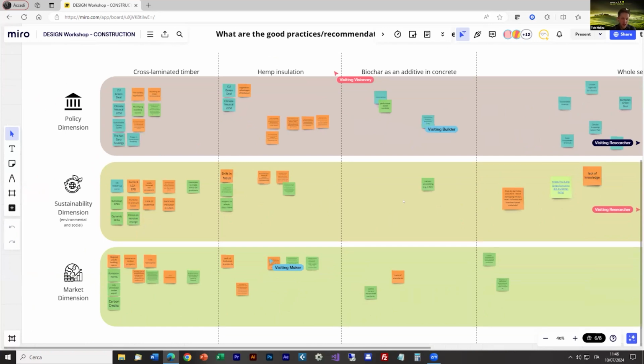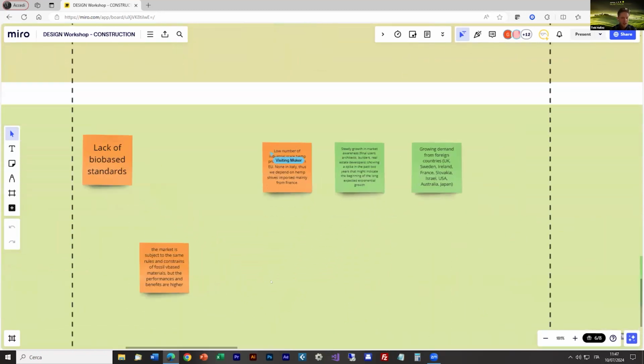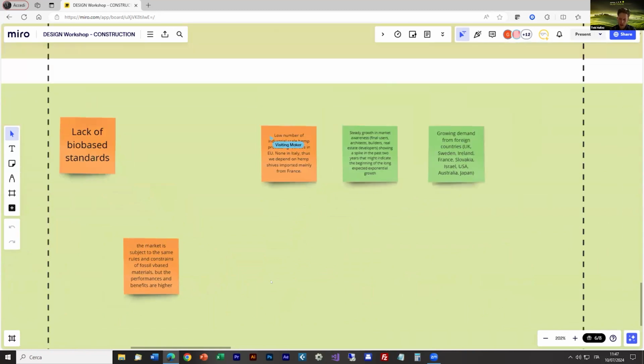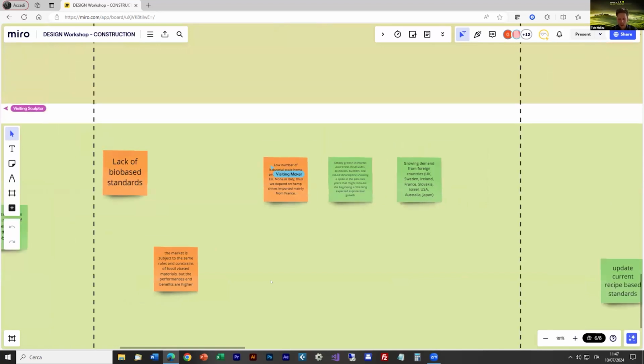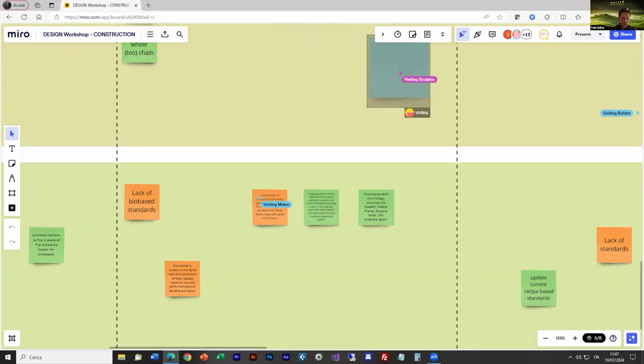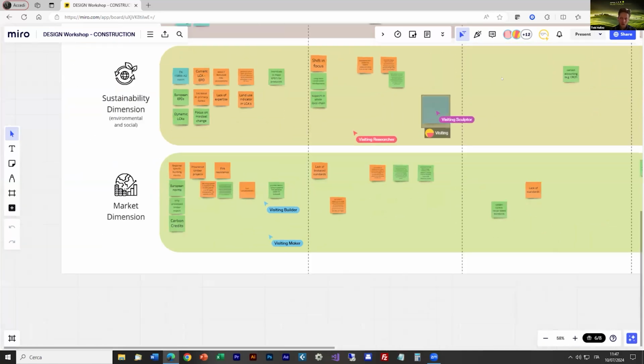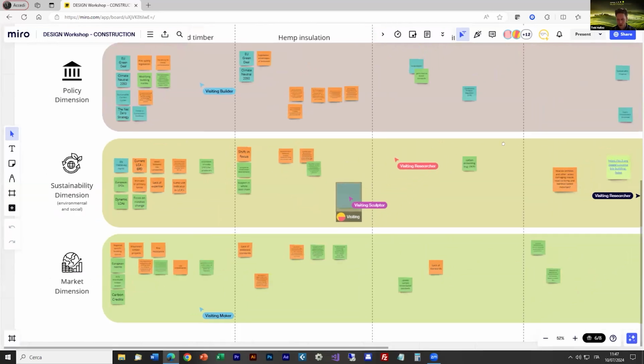So yes, well, when we look at circularity, it can still be kept when you look at reuse. I think Felix also mentioned this in his presentation, but if we start looking at designing our buildings with the idea that we can also disassemble them afterwards, then technically, although there are still some questions regarding regulations and certification of the reuse of materials, the CLT panel could be reused in a different construction or partially reused or redimensioned. The glue technically is of course a permanent connection that remains, but there is still a form of recycling, technically downcycling, where, for example, CLT can still be used for the manufacture of chipboard or OSB, other engineered wood products, but of course the connection between the timber is no longer usable.